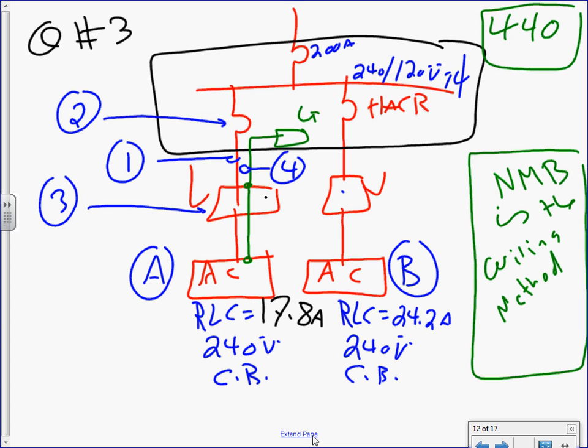Because conductors can be feeder conductors, service conductors, or branch circuit conductors. So when you go for interviews, or when you talk to your colleagues, always say, I'm sizing the branch circuit conductors. There are rules and regulations for this, for feeder conductors and service conductors, cool? So what we're sizing here is not the feeder, we're sizing the branch circuit conductors. So learn the terminology that we use in the code, guys. It helps you a lot.